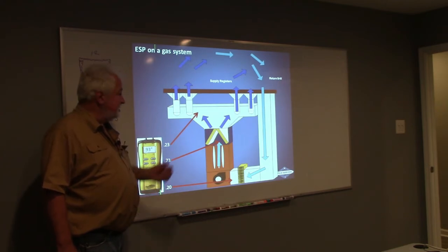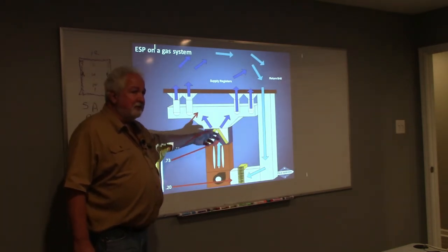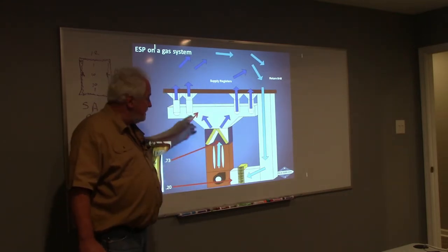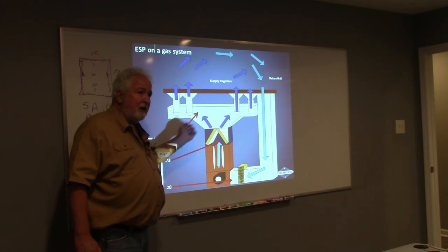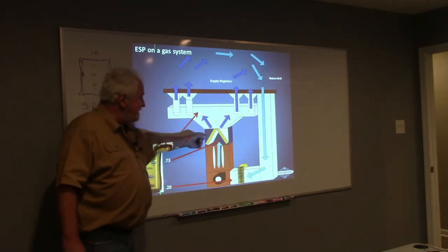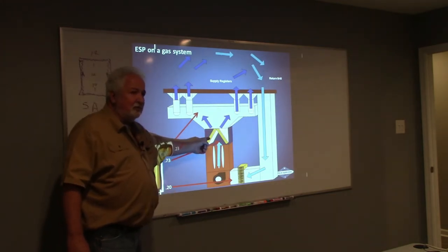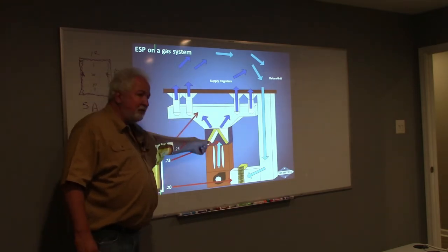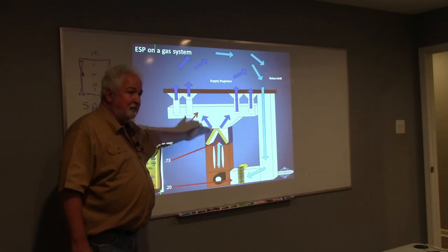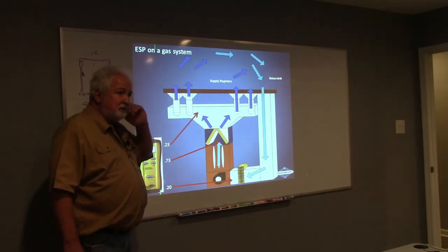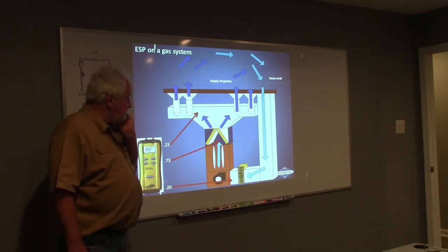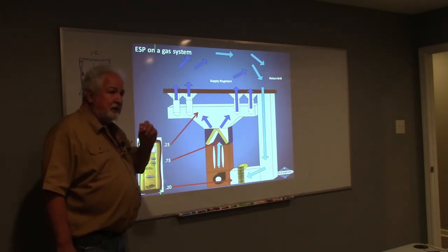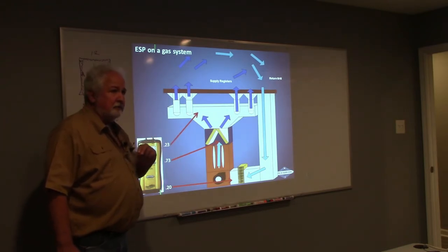But I couldn't get it out because I couldn't see, because I didn't take the panel off because they had it all pookied in and everything else, right? But real quick and easy, I was able to identify where my problem was on this system. And if I did get this down to about a 0.2 across here, that 0.23 plus my 0.2 would be a 0.43 now. Does that make sense? So yeah, we probably could straighten this whole problem out by just cleaning the coil. Do you see how this tool can help you out?